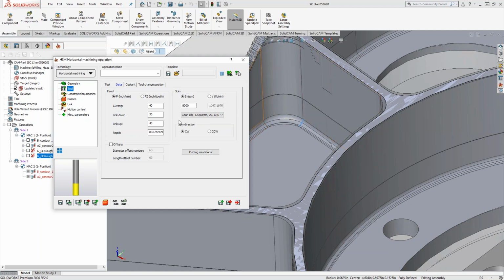Because this is an aluminum part, and I took it from his aluminum list. But basically, those are guides. You always want to double check your data to make sure the feeds and speeds are correct. But go ahead, Kevin. As a takeaway from this, I got told I had to dial down my feeds and speeds because I was going too fast for these libraries. So these are going to be much slower.